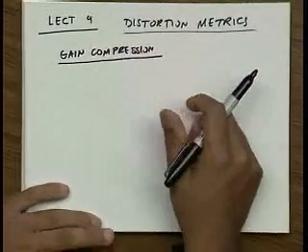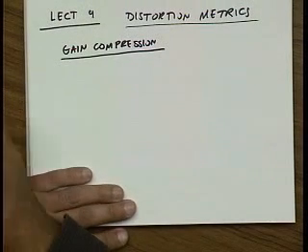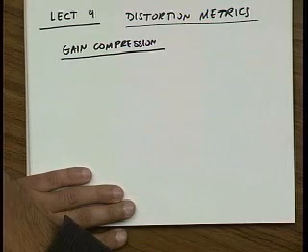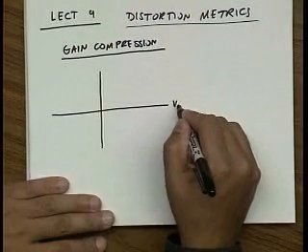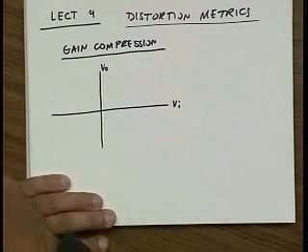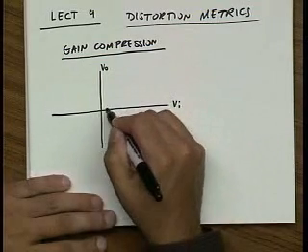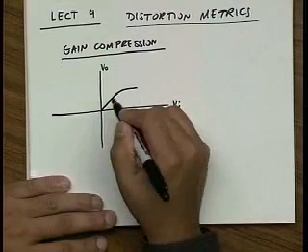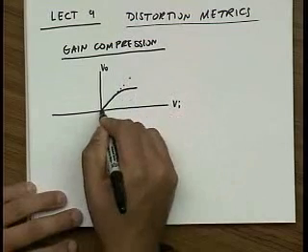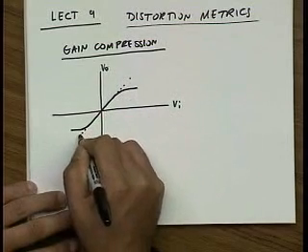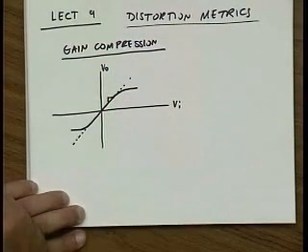Now the idea of gain compression is very simple. If you go out into the lab, in fact I encourage you guys to do this, take a commercial amplifier and plot the power gain. Well, first plot the output voltage as a function of the input voltage as you vary the input. So this is the input, this is the output. And this could be an AC signal, it could be a low frequency signal, but what you'll find, as we discussed last lecture, is that this output will eventually compress. And likewise in the negative direction it may do something similar. And so the apparent gain, the gain is proportional to the slope, reduces.